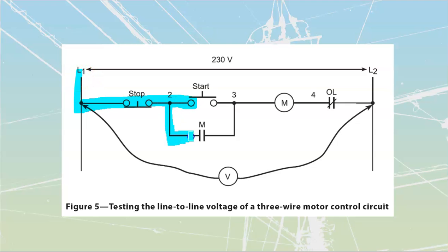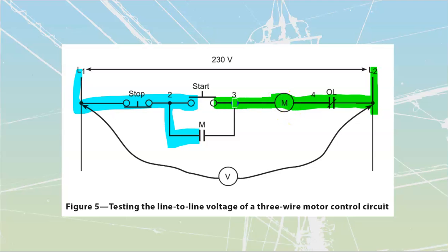So right now, in a normal circuit, I should have line 1 that will extend all the way up to there. Line 2 should go through a normally closed overload. It will pass through here. We won't be dropping any volts across here because we've got no amps, therefore there's no voltage drop. It's an open, and it's going to go all the way up to here. So under normal conditions, if all my components are good, the whole circuit at this point is open. I press the start. As soon as I press the start, current flow happens. So then we drop the source voltage over top of this and everything else happens.